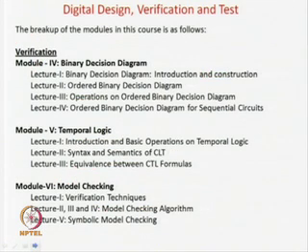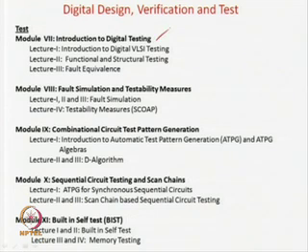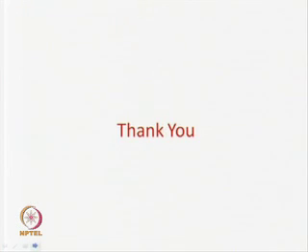Next we will have the verification part, that is, how automatic tools can be developed to verify each translation when you are going from one version of the circuit to another, like from gate level to RTL, from RTL to gate level, or from specification level to RTL level. In verification we will learn binary decision diagrams, temporal logic and model checking. Finally, in testing, we will have an introduction to testing, fault simulation, how you can generate test patterns for combinational circuits and for sequential circuits, and how you can test memories.